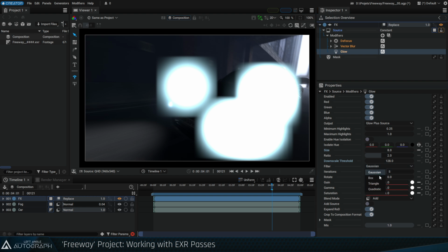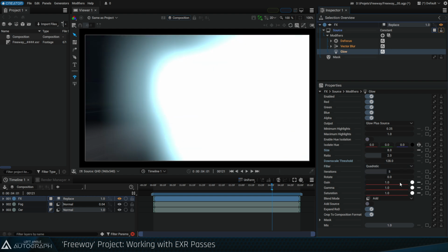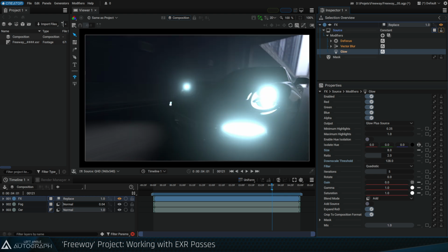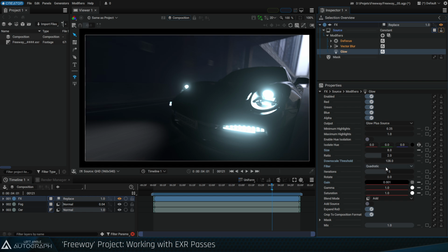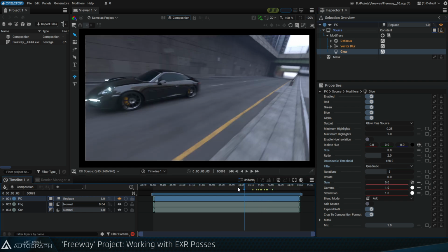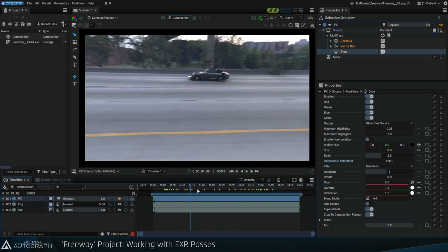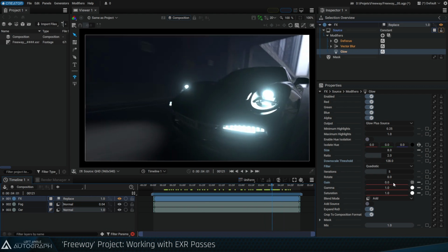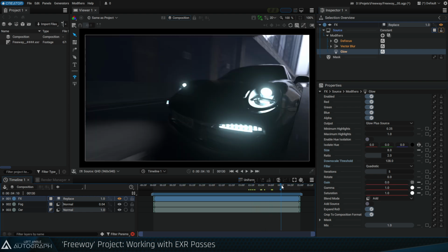Switch the filter to quadratic to produce a much more diffuse halo. Then reduce the gain value to make the halo dimmer. We're going to reduce this value to 0.001. The high light intensity produced by the glow is due to the fact that the initial pixel value was also very high. For this reason, the glow value must be precisely adjusted using the left and right arrows on the keyboard, then up and down to increase or decrease the value under the cursor.